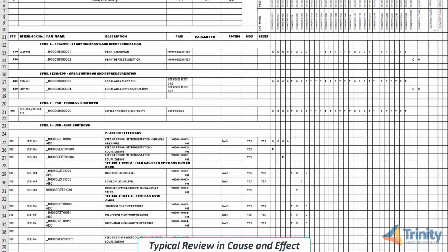If you look at the cause and effect we have received, it shows that some tags have resets and some have overrides. So we know you need at least two types of analog typicals. One where you may have the latch behavior with reset and one without that. You may also need a 2 out of 3 voted typical with reset and override. You can decide this just by looking at these fields.